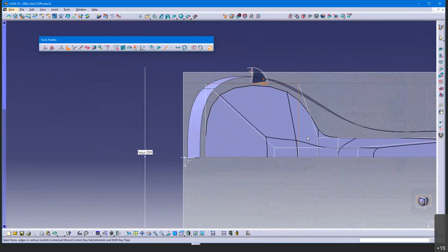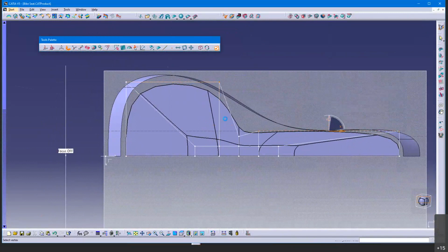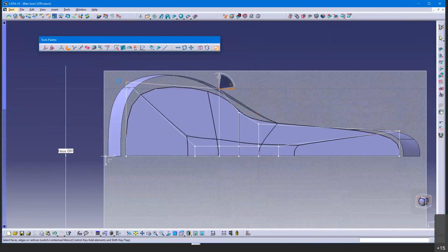I'm just manipulating here to get this close. You're either moving control vertices, or I guess you can play around with edges, control vertices, and you're trying to fit this in there. Just be careful with these end ones, because on these end ones you've got this normality on this curve.